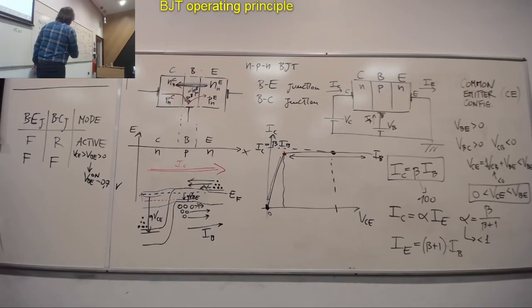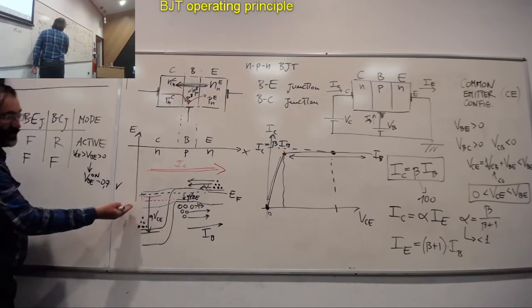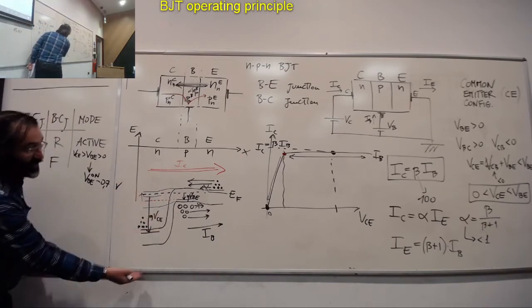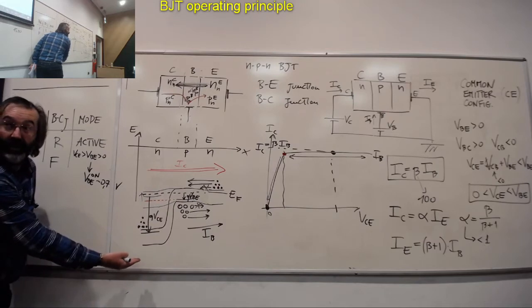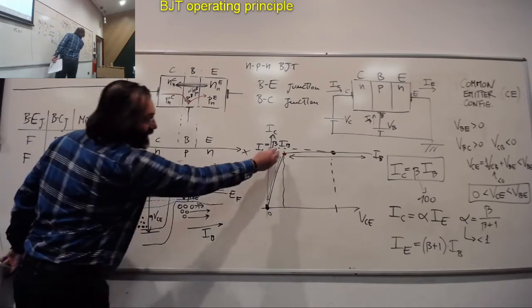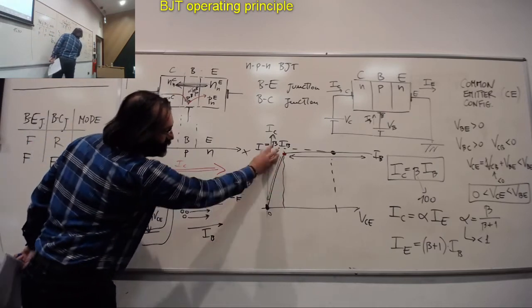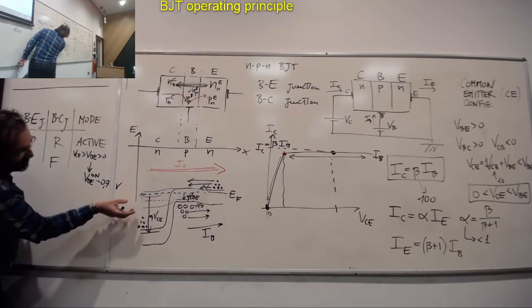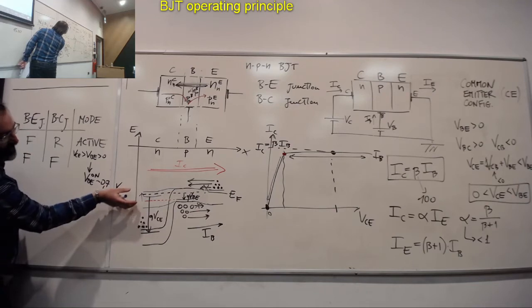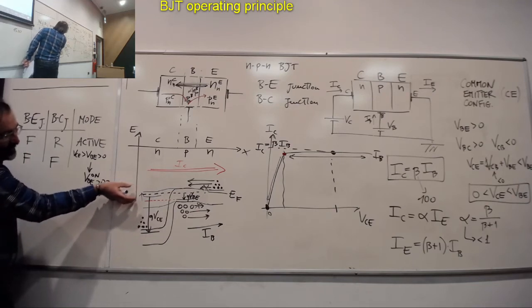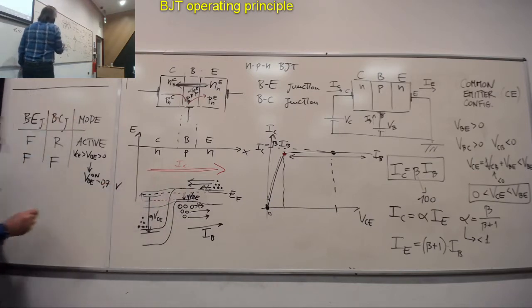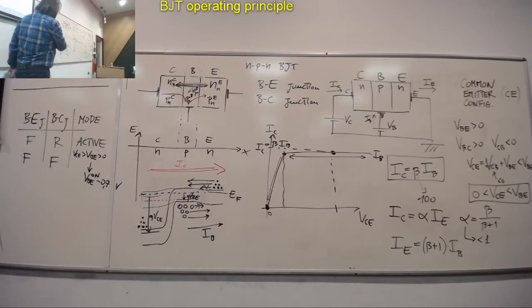It's not difficult to understand based on the fact that we said this huge current IC that we see is because there is this energy drop on the collector side. What we are describing in this region of the plot is that the collector energy diagram is moving and coming aligned to the base, the conduction band and the valence band roughly.